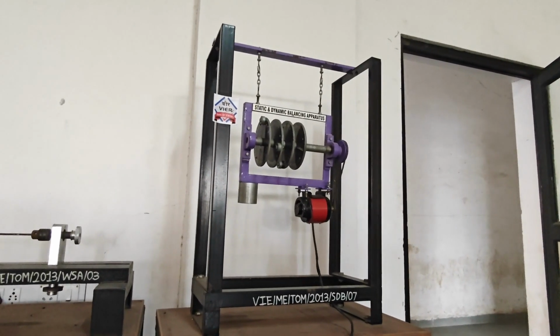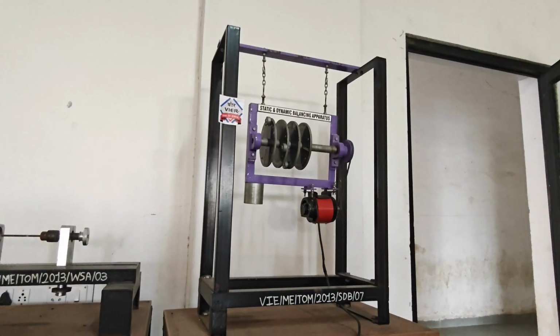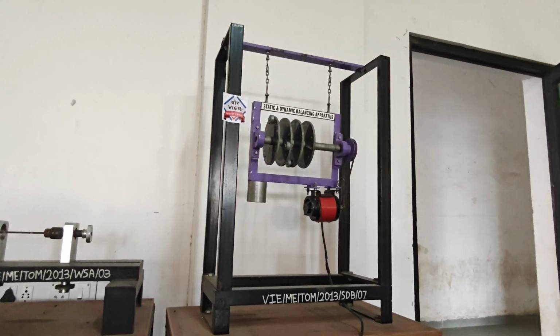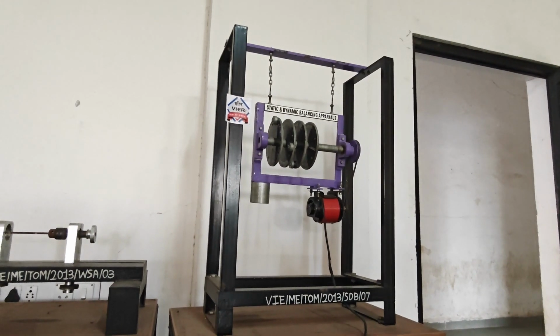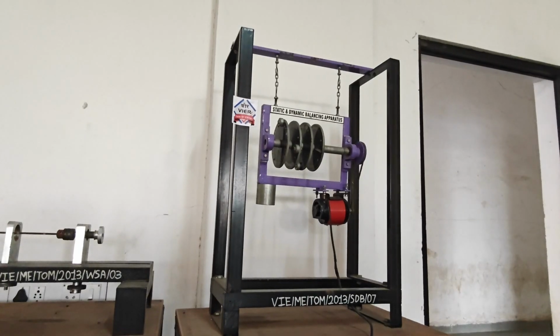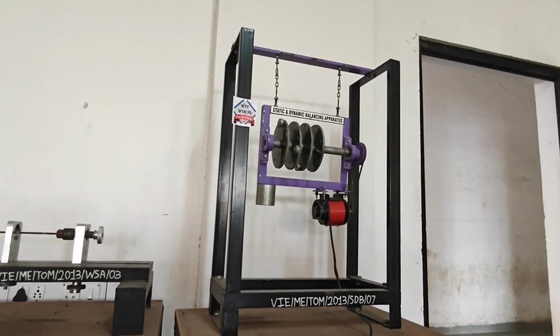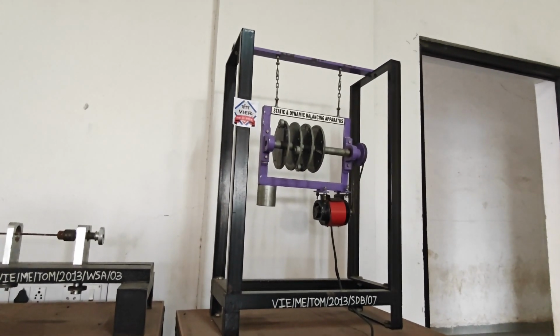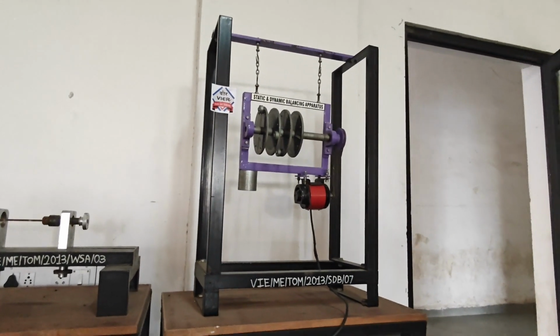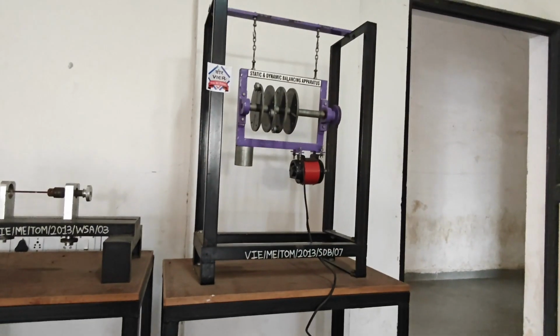For dynamic, mount the same masses on the balancing machine at their angular positions and radii. Run the shaft at low speed. Observe the vibration pattern or pointer movement. Using a vector diagram, calculate the position and amount of balancing mass required. Place the mass at the calculated position. Repeat the same process. Now we can start the machine, right?